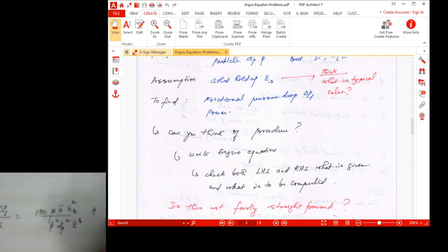So the second term, the coefficient is 1.75, because this is the inertial term or the kinetic energy term, so we can write it as rho u bar square. Here the denominator is just phi into dp. Now this again will be multiplied in the denominator by the cube of the voidage fraction or the void fraction, and in the numerator you will have the solid hold up. The power on the solid hold up is the same as the power of this. So this is how you can easily remember your Ergun equation.